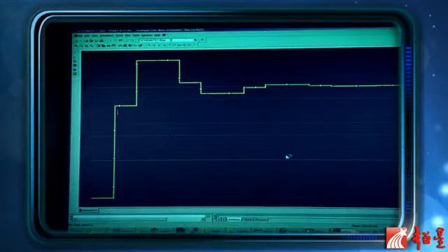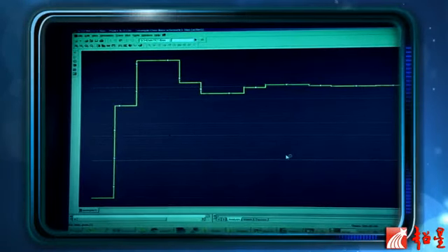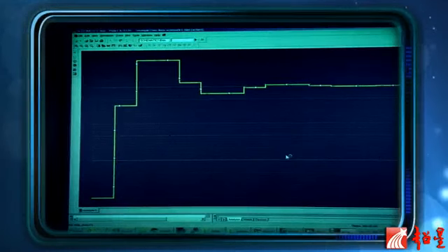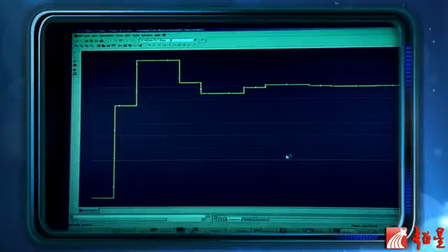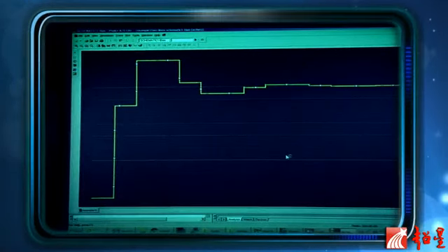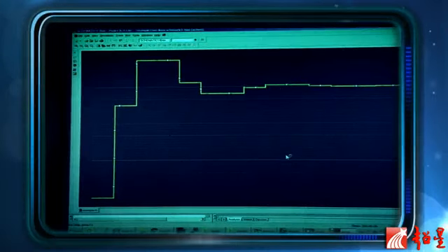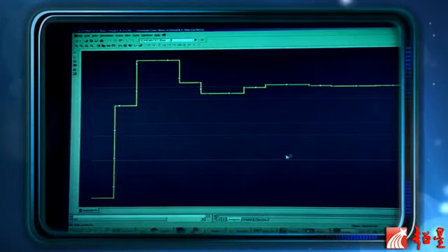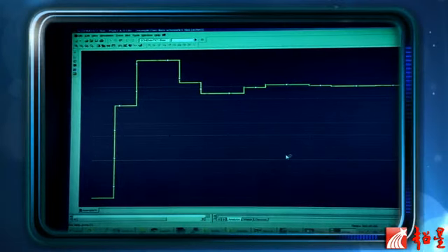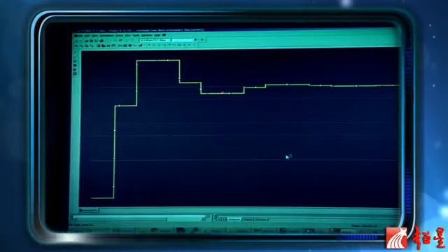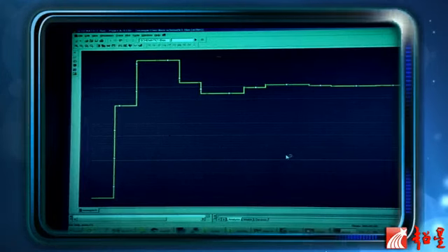So this is the waveform. Looks pretty strange, right? But that's what it is. Because of transmission line ringing effects, it's pretty hard to just look at the circuit to find out why it is like that. But once you do a simulation, you can see it's pretty complicated, right? The step function will start as a step, but it's going to be bouncing back and forth until it's stabilized at 4.5 volts. This is a so-called transient.